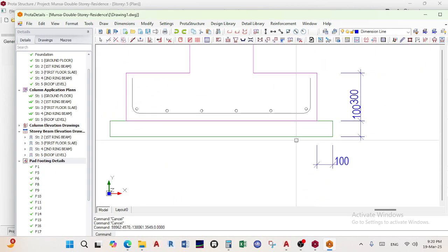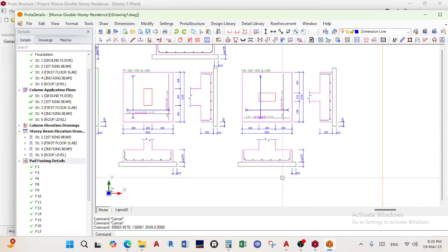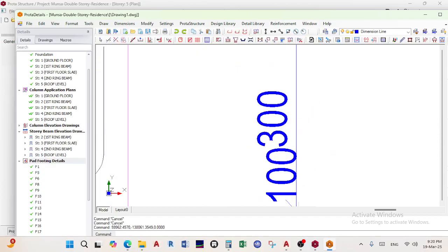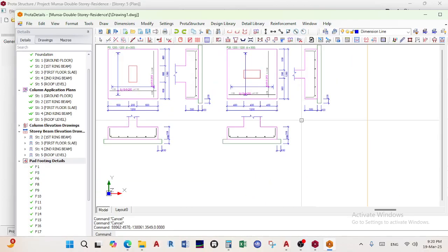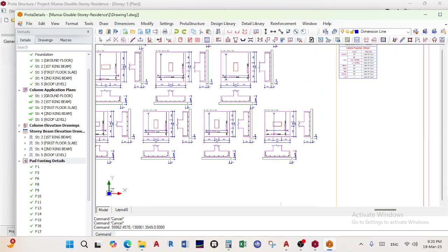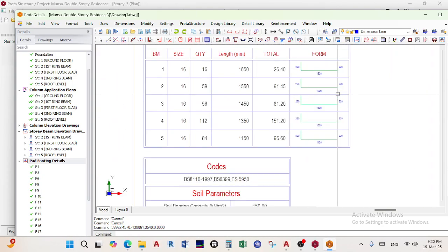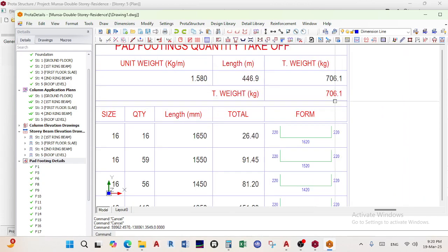And then it shows me that it's just one mat, that they are singly reinforced. Their doubly would have another mat there at the top. And then there goes Prota, not detailing properly, puts everything in one like that. But here it details properly. And then it also gives you a bar bending schedule, properly calculated.